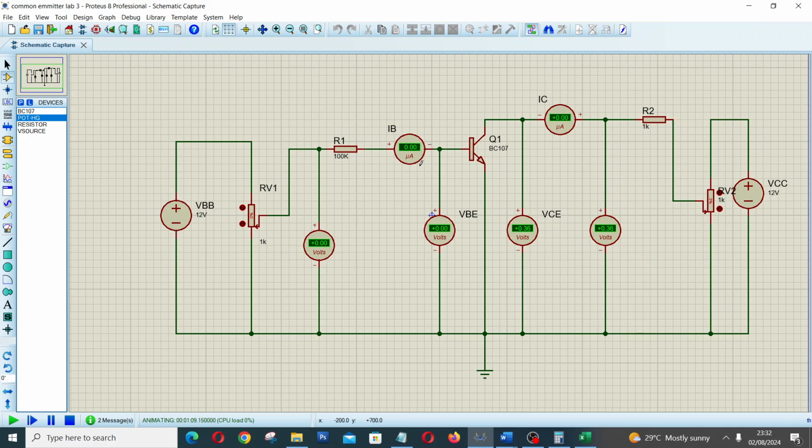So this is a forward bias condition. But the voltage that this transistor is receiving is not enough to set it up for operation. That is why you see that all the voltage generated by VCC is dropped at the base emitter terminal. No current is flowing through the transistor yet. That's why you see this guy recording 0 and this guy recording 0.